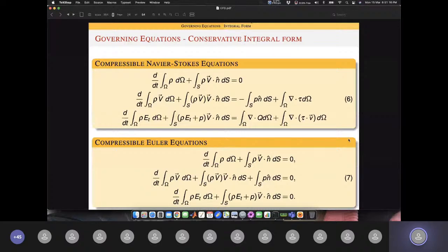Okay, you say that the rate of change of velocity of a body is equal to the summation of all the forces acting on the body. Now the body that you are looking at is the fluid here. So the left hand side of this equation represents your acceleration. Don't get panicked by looking at this equation. That's just an acceleration over there. The right hand side is all the forces that are acting on the fluid that you are looking at.